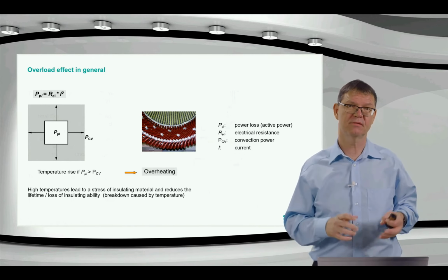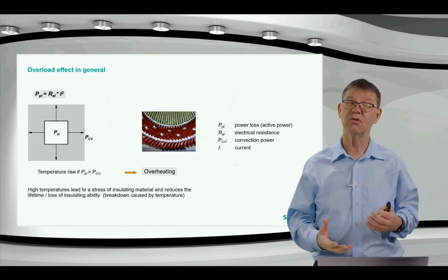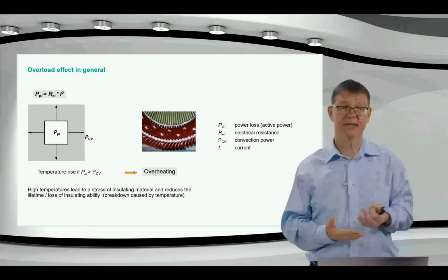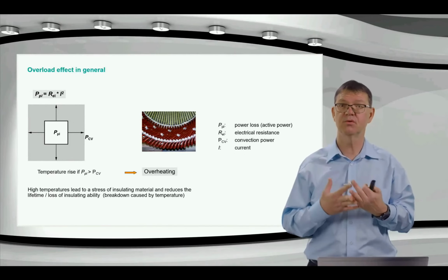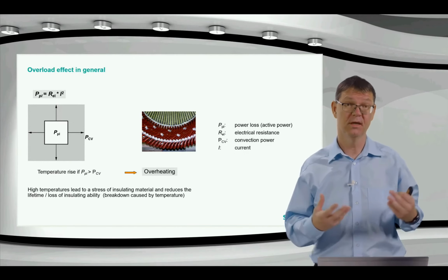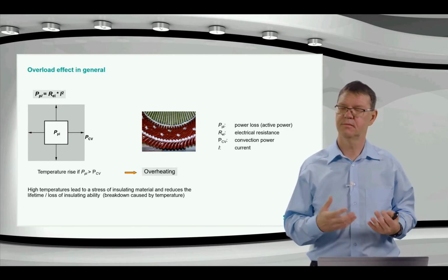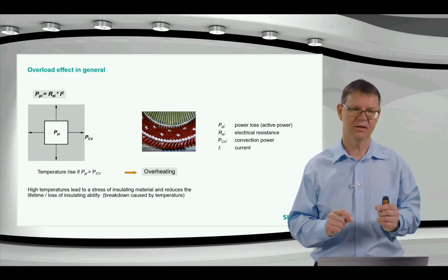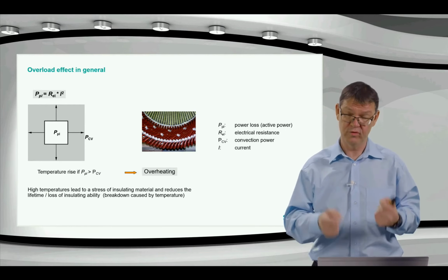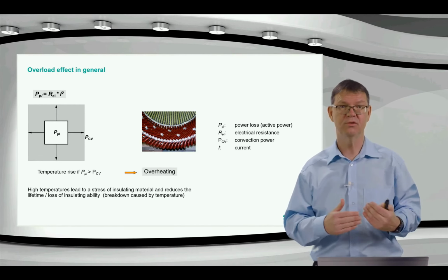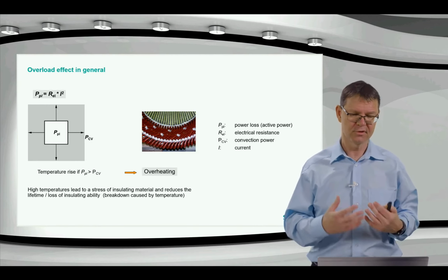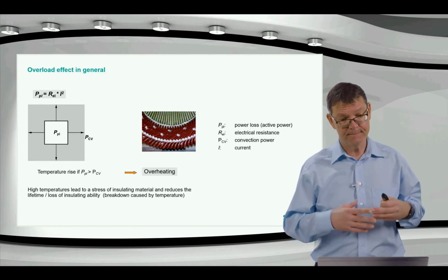High temperatures do not directly damage the motor, but they stress the insulation material, and this affects the lifetime of the motor. The higher the overtemperature, the faster the damage occurs, or the point where damage is reached. So therefore, we need to control that thoroughly here.